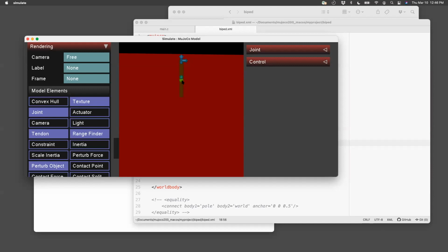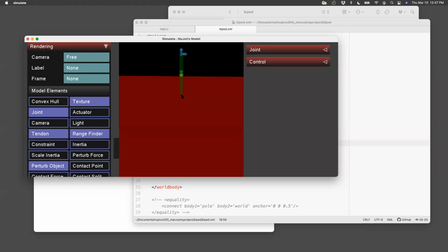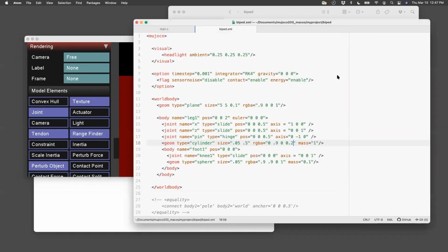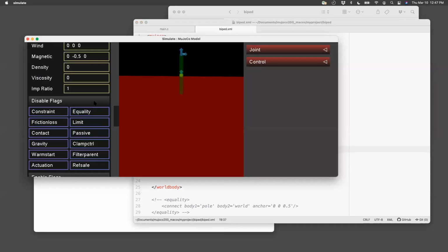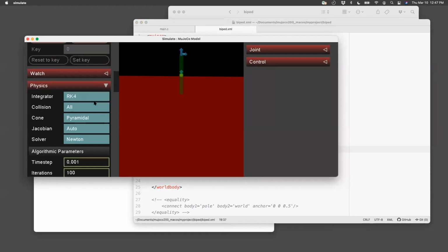So what we want to do here is perhaps move this down, and we need to decide how much clearance we want. So this distance is 0.5, and I want to perhaps move it to 0.75. So I'm going to move the sphere 0.75 down. So I go to sphere and I say minus 0.75, and then let's reload.